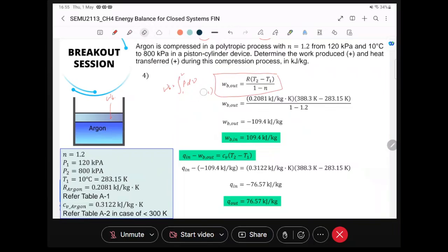There's a derivation of it, but I don't remember, to be honest. So if you're interested, you can find it out. But this is not even isothermal. Sorry, this is a polytropic process. It's not isothermal, not isobaric, not isochoric. Anyway, the boundary work is defined by an equation like this, which we most of the time just use again. Here n is the polytropic exponent.